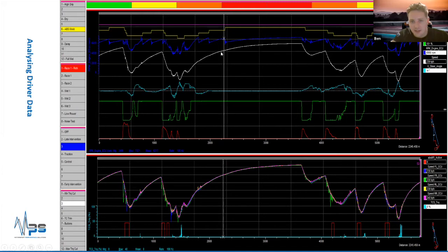This white line with an X is the live point which we're looking at, and it's at the end of the rising engine speed trace in blue. That basically means we've come to our shifting point, and you'll see in the next few data samples, working from left to right, that the driver has performed a gear shift. The gear's gone up and the engine speed has dropped. So that's just a brief introduction, but this is how I like to set out my driver page.